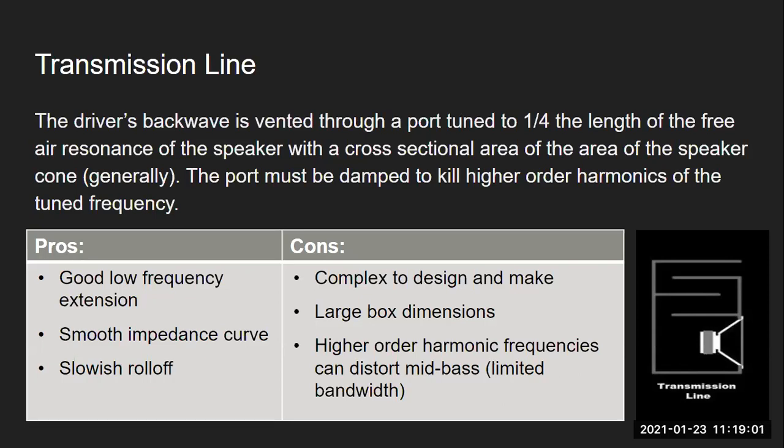You have to build for 30 hertz, let's say, right? If you take a quarter of that wavelength, it's somewhere around 8 feet. So you have to build a very long labyrinth, and typically it's done by folding it back and forth, and that requires a lot of internal cabinet components. And so it's not very scalable for volume production, and that's why you don't see it as much.